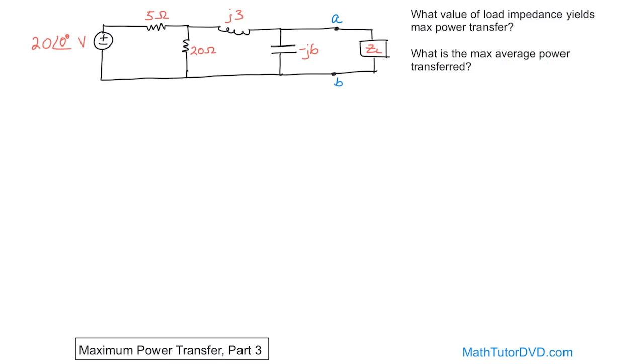So again, I'm going to reiterate that when you're calculating max power transfer, you only care about real power, watts. You're generally not concerned with Q because that's an oscillating factor anyway. You want to adjust things so that you get the maximum number of real power watts delivered to your load.